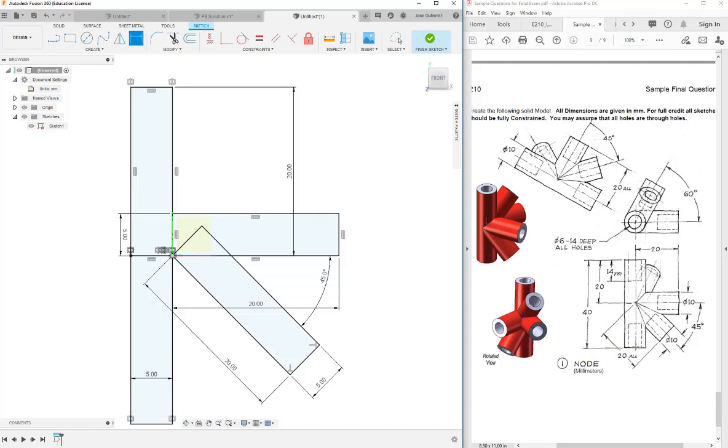And what we see is a bunch of blind holes. And so it seems like they did not design this for manufacturability. There should be tapers on these. I'm going to go ahead and use the hole tool after the fact. But if you wanted to, you could actually just embed rectangles in here and not revolve those. And so I'll do one of those and that would be perfectly acceptable solution. So actually I'll just use the line tool because I don't need to add extra lines here.